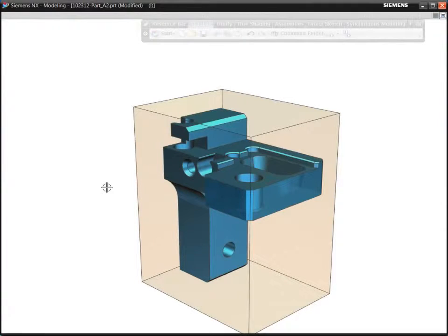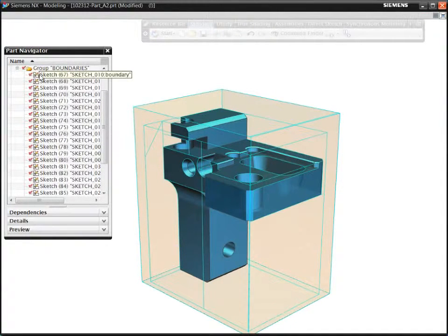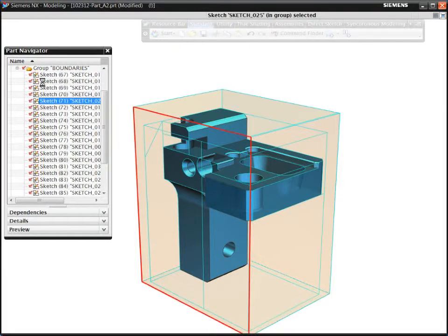Volume-based milling is a fast and intuitive way to program parts with prismatic features. You can quickly create operations by simply specifying the volumes to be machined. To program prismatic parts using conventional methods, you typically need to create multiple containment boundaries. These boundaries are necessary to specify the machining volumes.